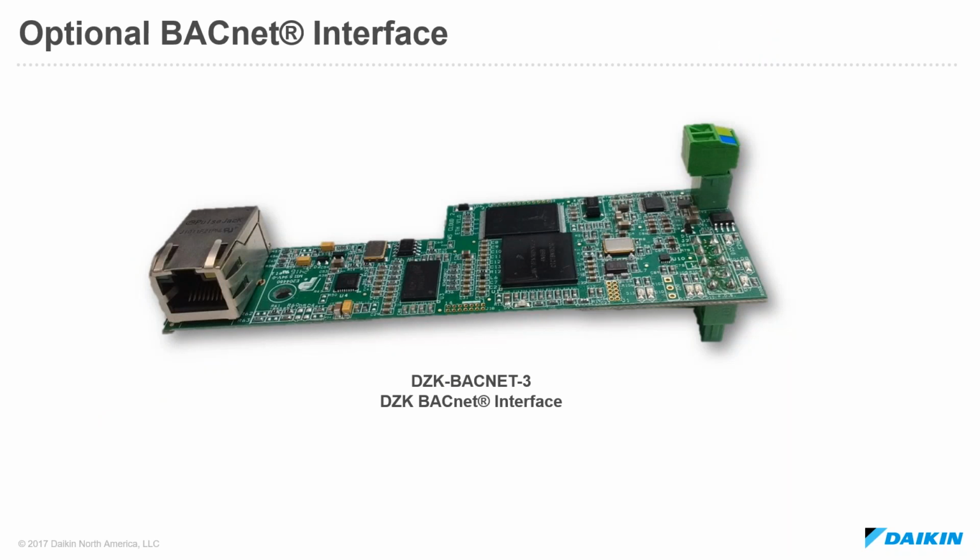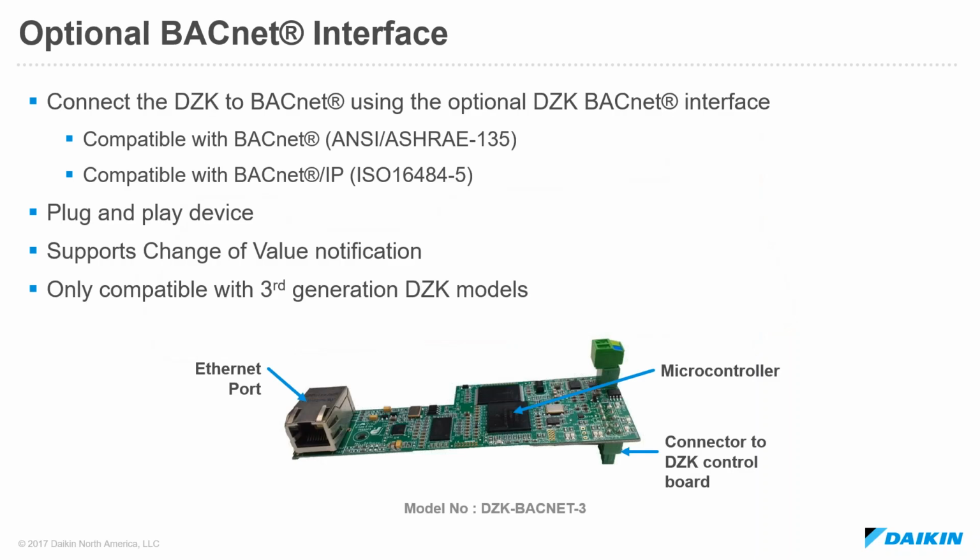So the BACnet interface is an optional add-on or field installed addition to the DZK. It's a small plug and play card that plugs right into the DZK's main board. So it installs directly into the enclosure. There's nothing additional needed to bolt on to the DZK in any form or fashion. We just plug this BACnet interface directly onto the DZK's main board.